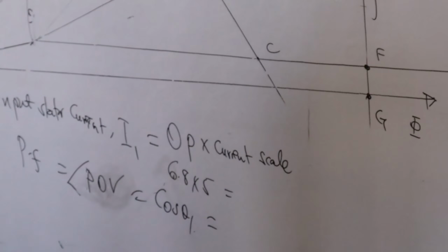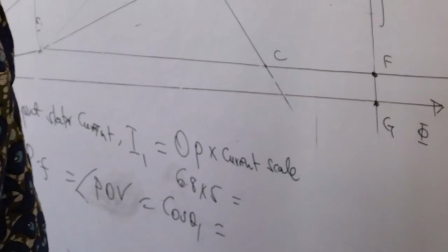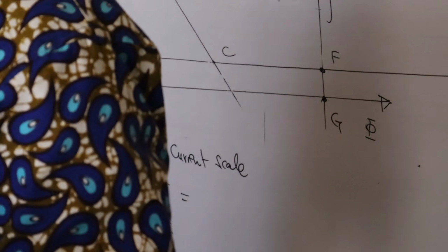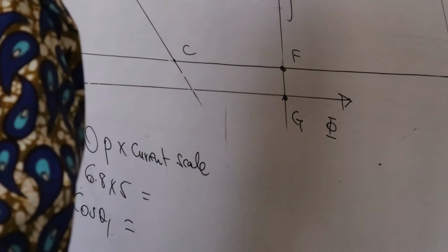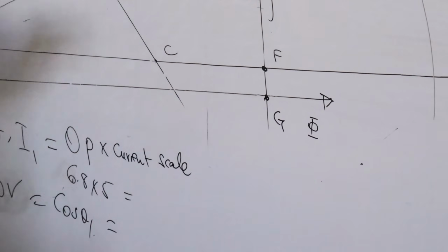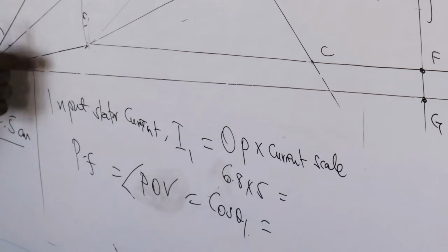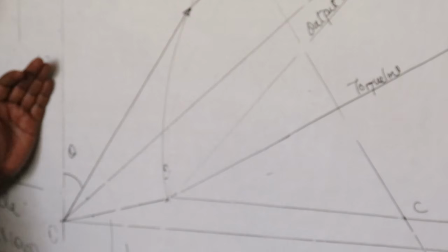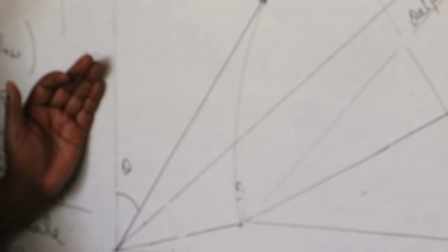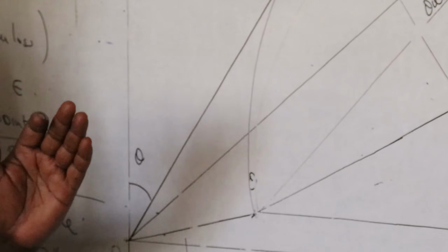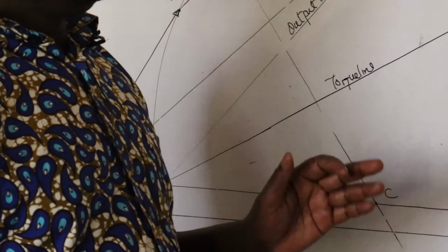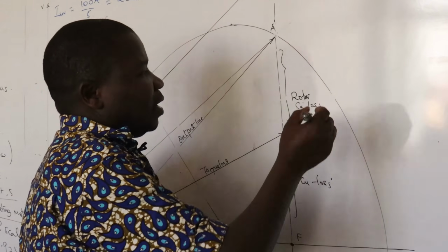Question number 2, power factor. I've said the way you are measuring the angle, this angle, the cos of it is the power factor. Lag. Remember to write lag.